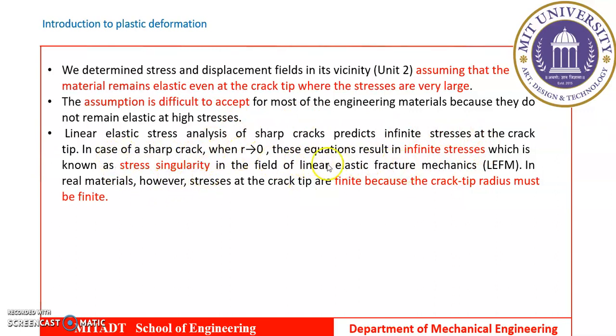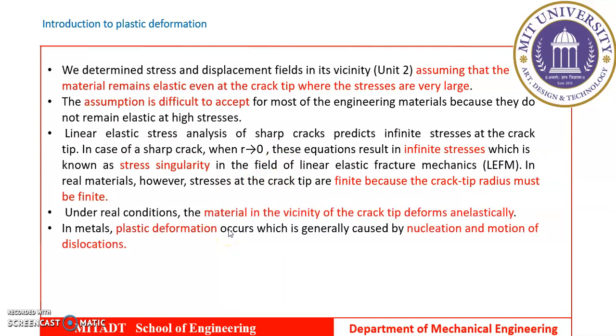We have seen the concept of linear elastic fracture mechanics. But in real materials, the stresses are not infinite, they are finite, because the crack tip has a certain radius, which is a finite number. Thus, in real conditions, the material near the crack tip deforms inelastically, that is plastically. We have seen the mechanism of plastic deformation, which is nothing but nucleation and motion of dislocations.